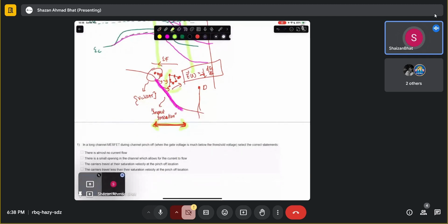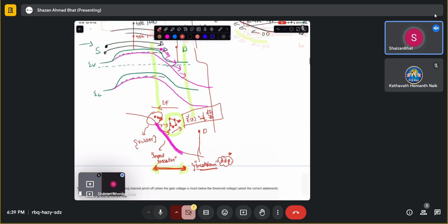You won't allow the cascade chain reaction of electrons hitting other electrons to continue. Maybe one electron can produce two, two can produce four, four can produce eight, and then it will stop, if you have made the length of this region up to this point. That means the length is a very important parameter in deciding the breakdown voltage and other properties of this device. So remember this, because I guess it will be important for one of the questions in this.